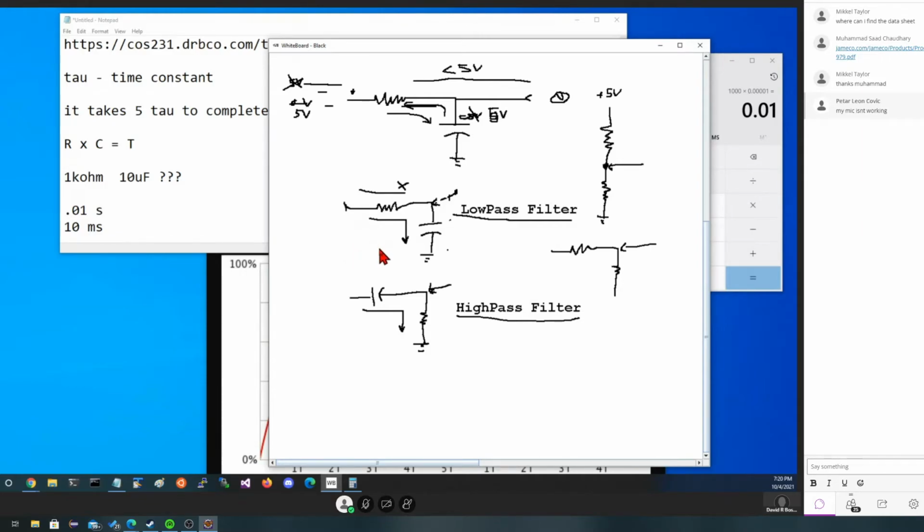Well, depending on whether or not you've had calculus, it might jump out at you or it might not. This circuit is performing integration. Meaning if I have a sine wave across time, it's going to fill the bucket, drain the bucket, fill the bucket, drain the bucket. It's basically going to integrate so that the area under the curve, high and low, offset each other.